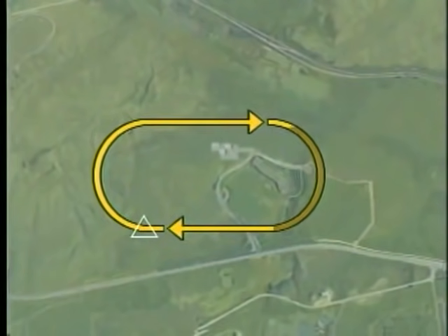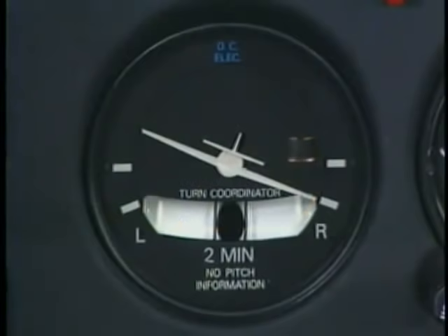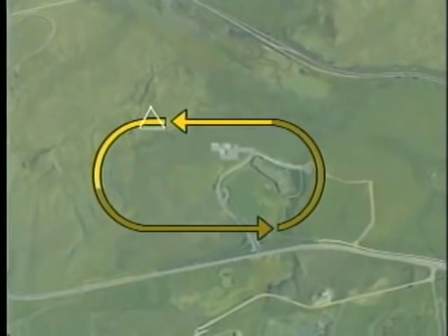While in a standard holding pattern, all turns should be made to the right. These turns should be limited to a standard rate or 30 degrees, whichever is less. Non-standard patterns use the same procedures. However, now you make the turns to the left.